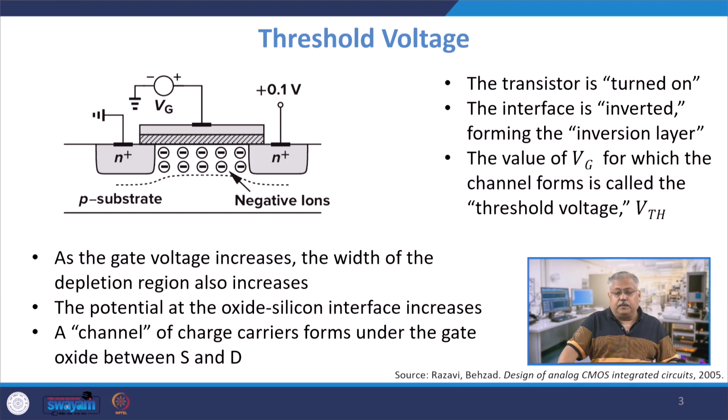Let me now come to the threshold voltage concept, which I have already discussed, but nonetheless we will do a small threshold voltage concept. The concept of threshold voltage is defined as something like this. We will not take the route of the energy band diagram, but we will talk in terms of the number of charge carriers. Now, I define the threshold voltage as that minimum gate voltage at which the volume just below the silicon dioxide interface has the same number of electrons per unit volume as there were holes initially. You got the point?